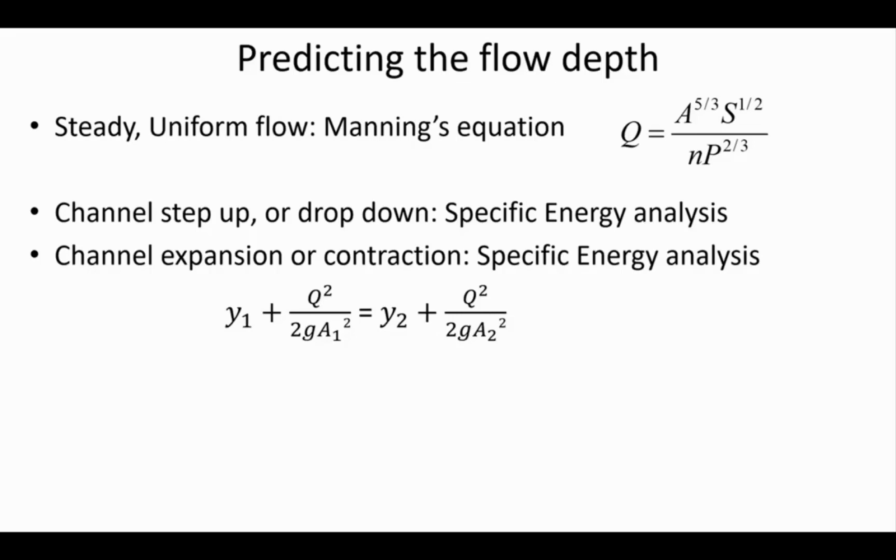Our method there was to assess whether we had super or subcritical flow upstream, and then downstream, we set up these cubic equations, found the roots, and then we'd know which root to select based on whether conditions had previously at the upstream location been supercritical or subcritical.